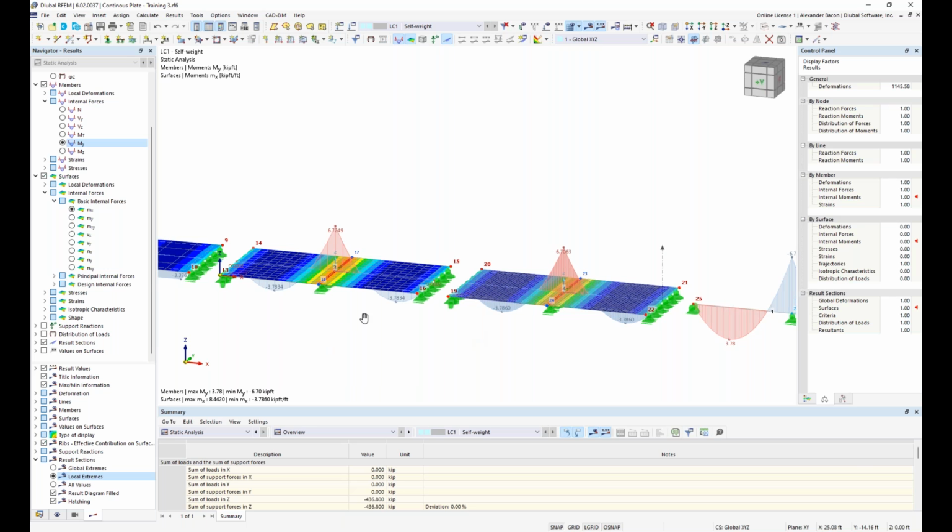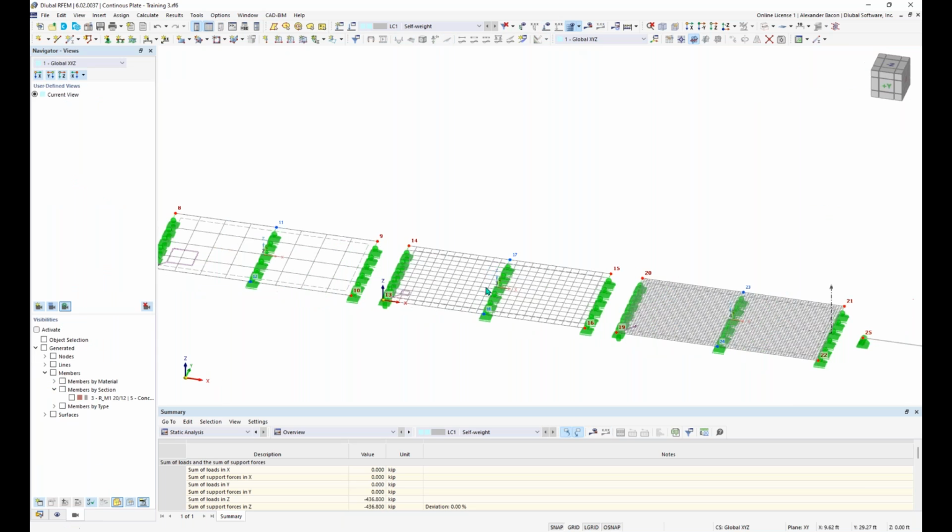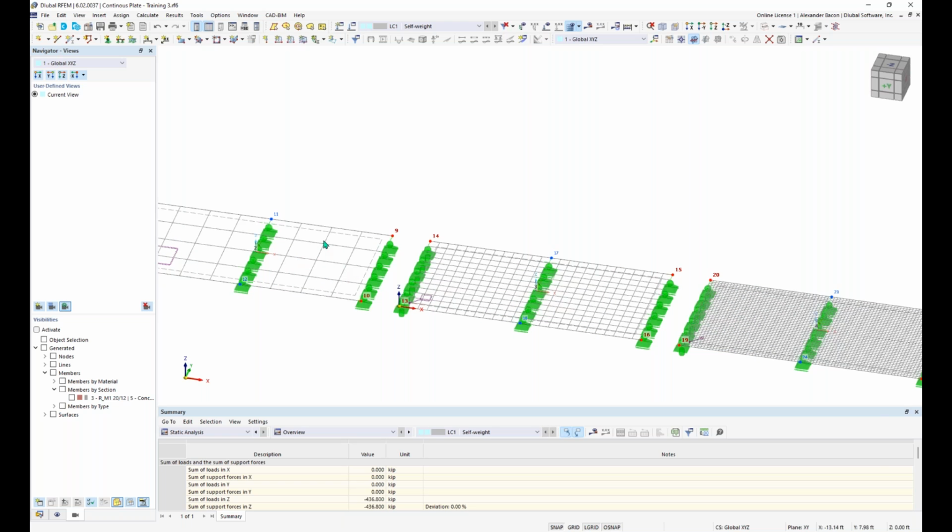And so what I would recommend is something like the mesh in the third example here. And a good rule of thumb is to have at least 4 FE mesh blocks between any given span or boundary. So this second surface here would be the minimum of what I would recommend.